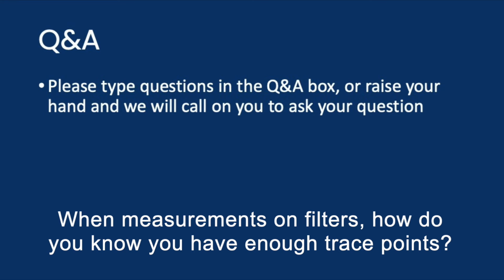Probably the best way to address that is to initially load it up with a lot of points, throw out a number like 10,000 points or something like that, or frequency spacings that are very narrow. And again, that's all going to depend on what frequency range we're talking about, megahertz or gigahertz. But anyway, as a general approach, load it up with a lot of points so that you get very detailed information about the shape of the curve.